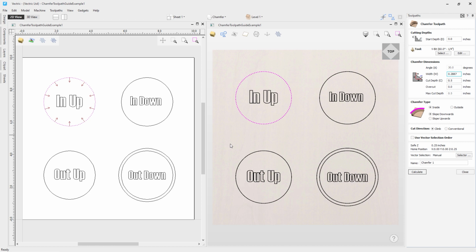So what the overcut will do is it will allow you to compensate for that by moving the tool so you can run the edge of the flat along the line, and it will also cut a bit deeper so you will not be left with a step. Now you may want to run a few test parts to ensure that the overcut distance is correct for your tool. So if you want to take a look at adding an overcut of 0.1 for example here, or even a much smaller value of 0.01. Keep an eye on the max cut depth field. You'll notice it changes very slightly. We can delete that out of there for the moment.